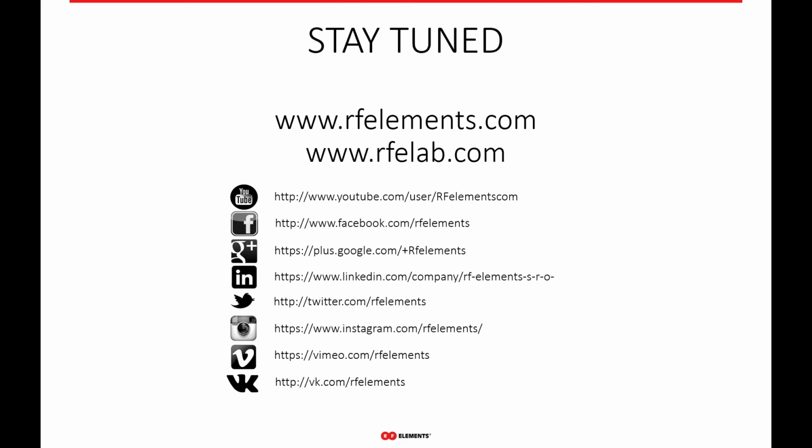And its beam efficiency falls within the kind of range that you see typically for other patch array antennas out there. Now, we've done a lot with the integrated back shield, which helps to alleviate a lot of the parasitic side lobes that are created with the traces that feed all the patches that create the beam for you. So our beam efficiency is higher than some other sectors out there, but it's nothing like a horn. Again, the efficiency is nowhere near as high as our horn specifically, again, because it's a patch array.